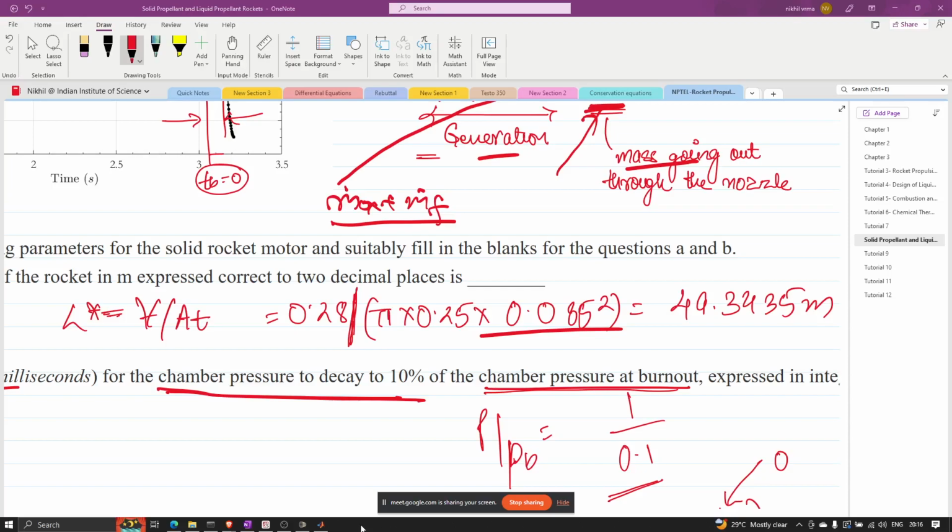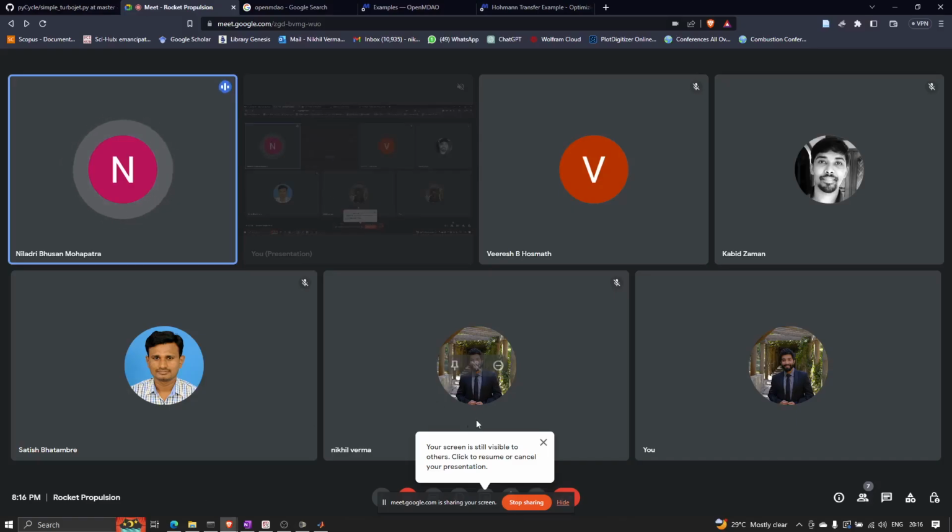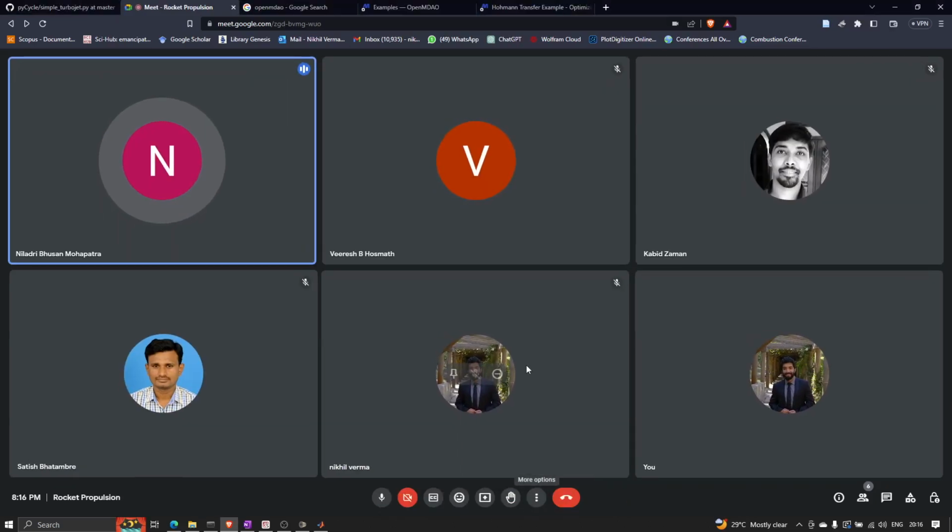Also, one more doubt I had. The mass, you told, is varying. Instead of modeling how the mass enters into the chamber, I will take the valve as my control volume and model there itself. The moment I give the signal to open the valve, manually or with a solenoid electronically, it will take some time to open.